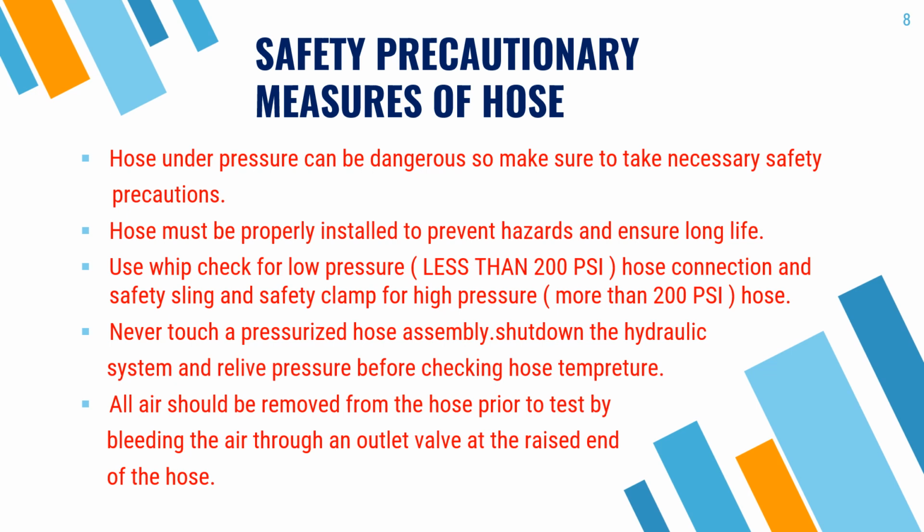Never touch a pressurized hose assembly. Shut down the hydraulic system and relieve pressure before checking hose temperature. All air should be removed from the hose prior to the test by bleeding the air through an outlet valve at the raised end of the hose.